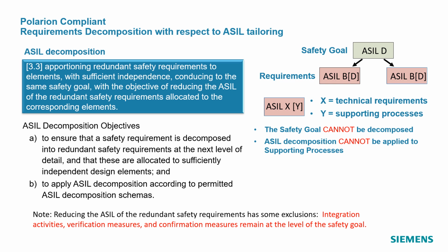We can break those ASIL up into two smaller ASILs that meet the technical requirements of the parent. The process ASIL cannot be divided since all processes have to meet the ASIL of the safety goal.